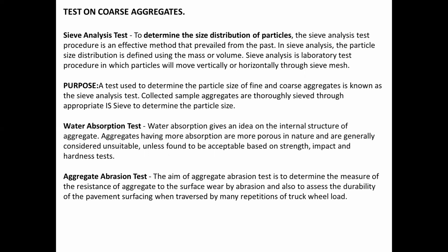And then we also have the water absorption test. It gives an idea of the internal structure of aggregate. Aggregates having more absorption are more porous in nature and are generally considered unsuitable, unless found to be acceptable based on strength, impact, and hardness tests.